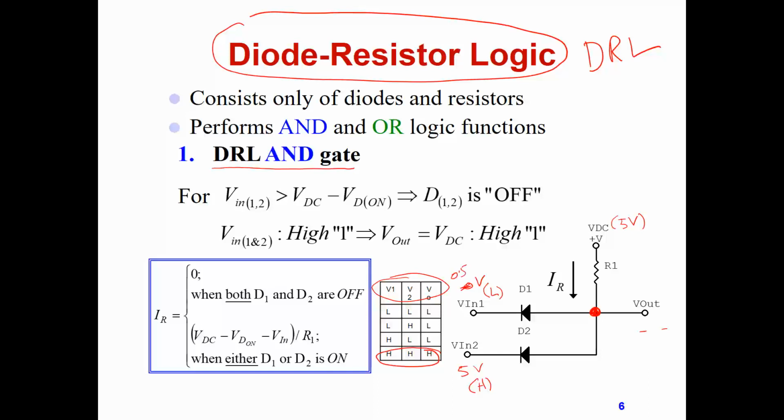really matter. Since this is low voltage, there will be a conduction here, because this node is more than the other node across the diode by 0.7. It will conduct until there is a drop of 0.7 across the diode. So this point here will have a voltage of 0.5 volt from the input plus 0.7, which equals 1.2 volts.